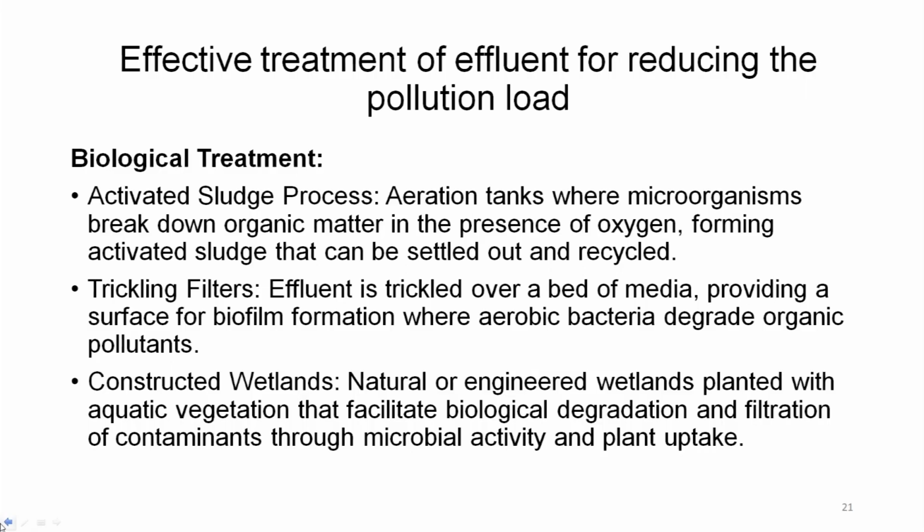Biological treatment: activated sludge process, aeration tanks with microorganisms breaking down the organic matter in the presence of oxygen, forming activated sludge that can be settled out or recycled.